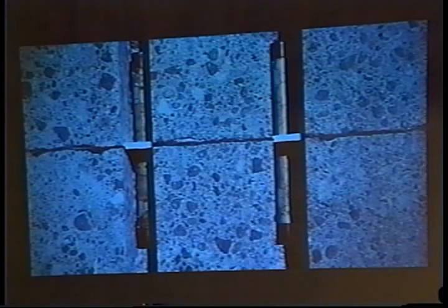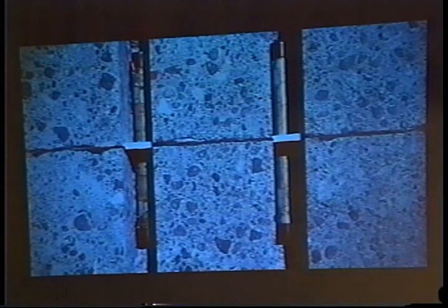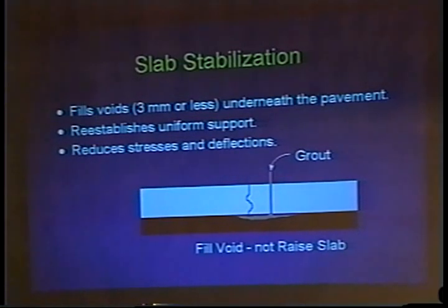Clean that up. Place the dowel bars back in there. They have chair assemblies that they mount these dowel bars on, and then a strip to reform that joint. So again, like I said, you don't get point-bearing load across there. You want to establish that joint exactly the way it was. The material you'll be putting in there will be a type of material that allows for this quick setup time, high strength, similar low shrinkage type of characteristics. And that'll establish your load transfer across that joint.